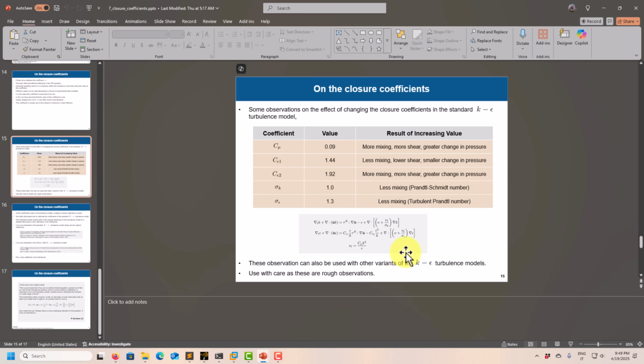We know that in this formulation of the turbulence model, it directly affects the turbulent viscosity, so here you have the effect that will happen. On a steady case, we saw some cases that you have some diffusion in the wake, in the shear layer. So probably readjusting these coefficients can get a better matching with the actual observations.